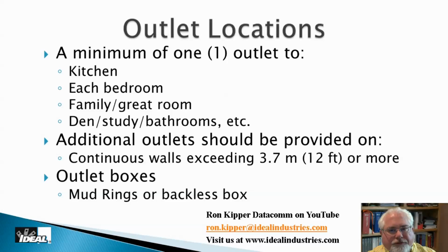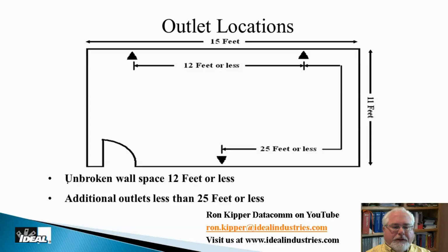Okay. The standard also suggests that if the room is big enough, we would put more than one outlet in the room to eliminate the need for extension cords. Kind of like the code book says about electrical outlets, same idea. So if that room is big enough, we would actually pull 3 different poles to the room itself. That's 3 separate poles, what we call home running of cable. It's a dedicated line of wire.